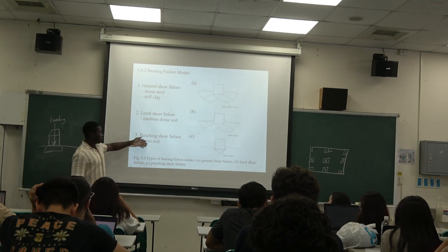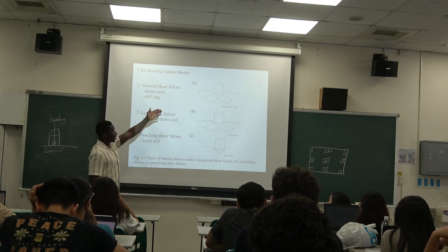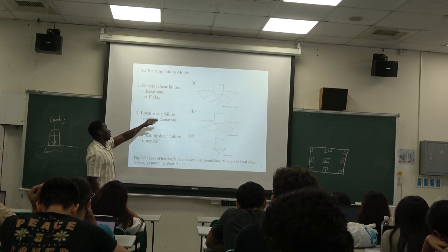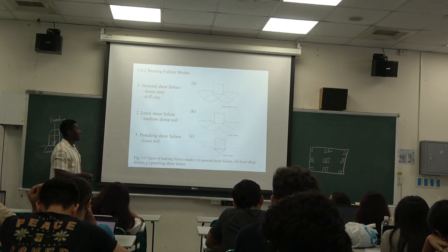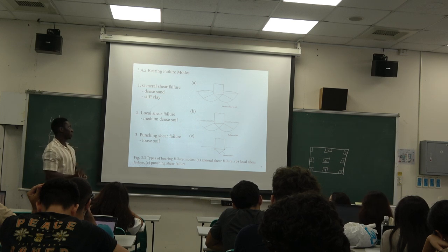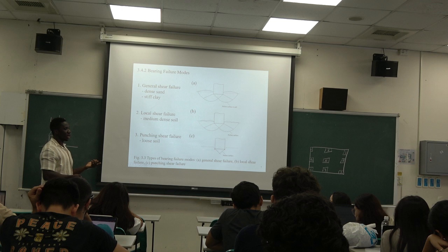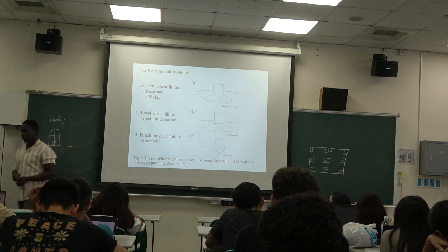Okay, so by seeing that diagram, you should know, okay, the soil I'm dealing with is dense or stiff clay, or like that, you know, okay, that should be a medium dense. Or if you experience punch, then you're like, okay, that should be loose soil.